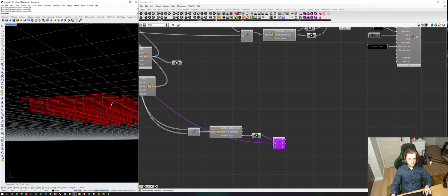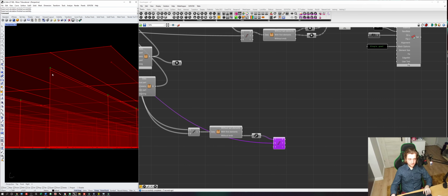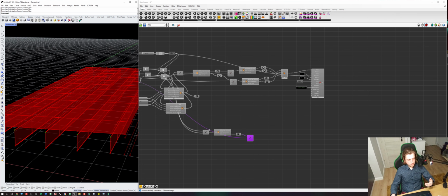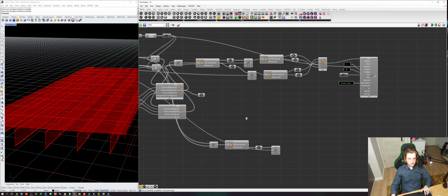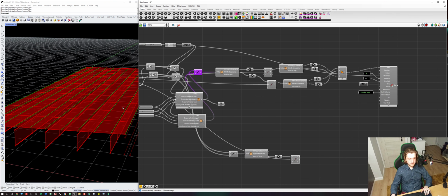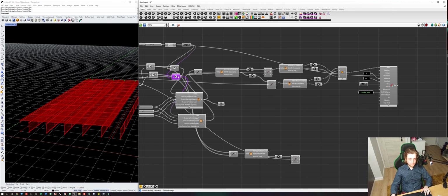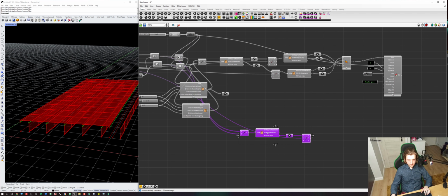So now the division is done. It's exactly as it was for the top flanges. And now we have to repeat this process for the top lines. So we could use this one, but it will be just easier to create lines between those 2 points set as we did previously, but without the division between the points.